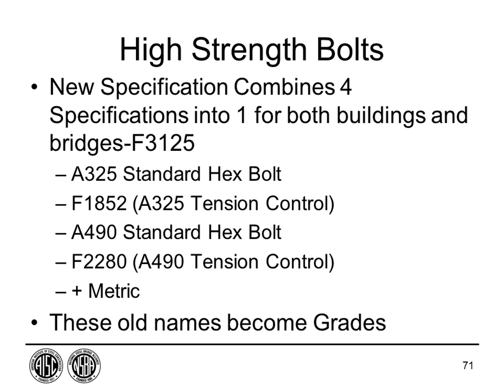There was some early research done that showed if you had large edge distances that you could get pack rust behind them. So there's a limitation in AASHTO on the edge distances and also the center-to-center spacing of the holes to prevent that. What we found in the research that we did, where we actually weathered connections and every day would go out and water them, is that we had no problem with pack rust or any bolts popping off because the bolts were properly installed.